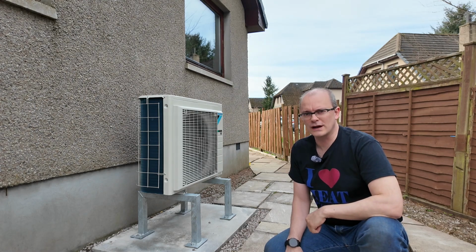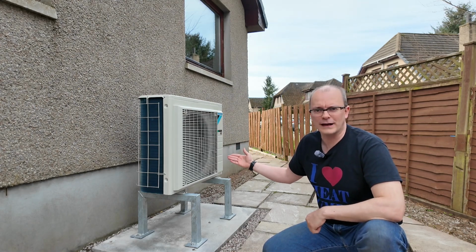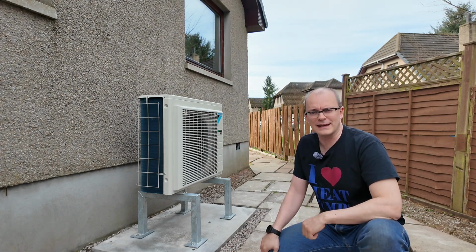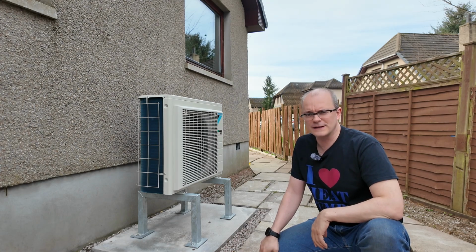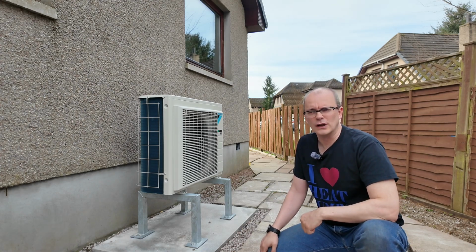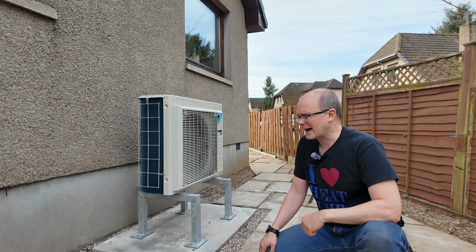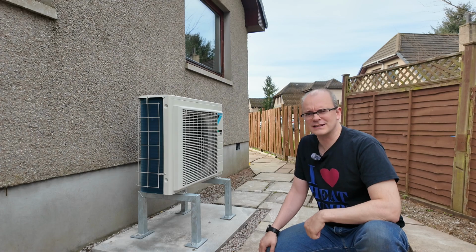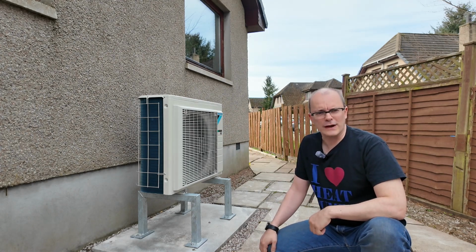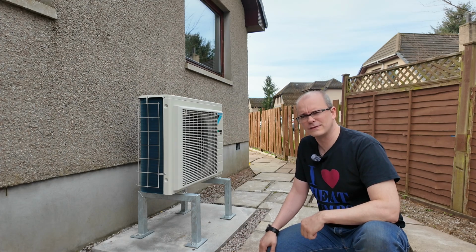Now, in this video, we are going to be looking at a tool which I've created for analysing the behaviour and performance of my heat pump. This extends on from the analysis which I performed in a previous video, but now I've made it much more easy to access and much more digestible in a form which I think could be useful for other people in future. Now, during that analysis, we discovered certain features about the heat pump which were a bit unsettling. The performance of this during milder weather, when it's about 10 degrees, was a lot worse than what it was when the temperature was colder, and that was very curious.